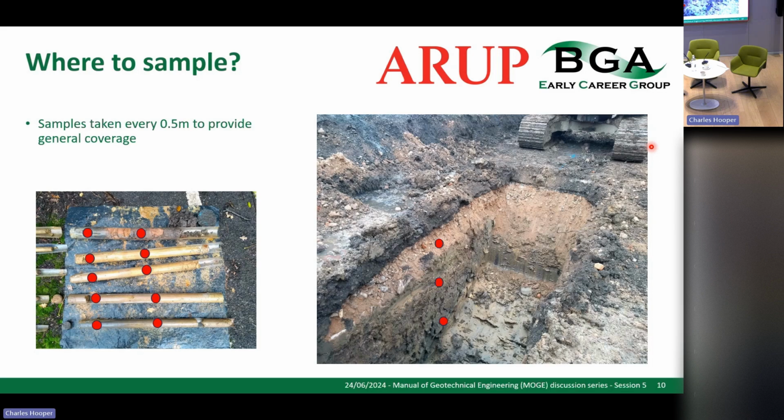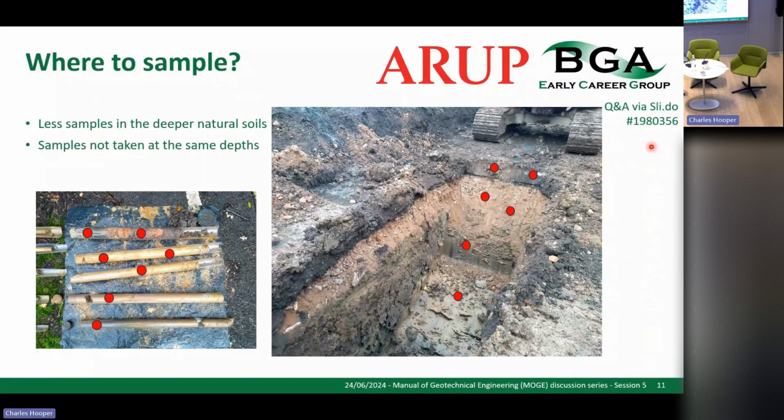For our trial pit, though, more importantly, you can see here, if we just do our half meter interval for testing, we've missed that top layer entirely. We have a single sample of the underlying material. But when it comes to assessment, when we actually have to look at what the risks are from that top made ground, we can say it's visibly different, it's a different material, and we wouldn't have a sample from it. So it's taking a step back and looking at a bit more of a nuanced approach.